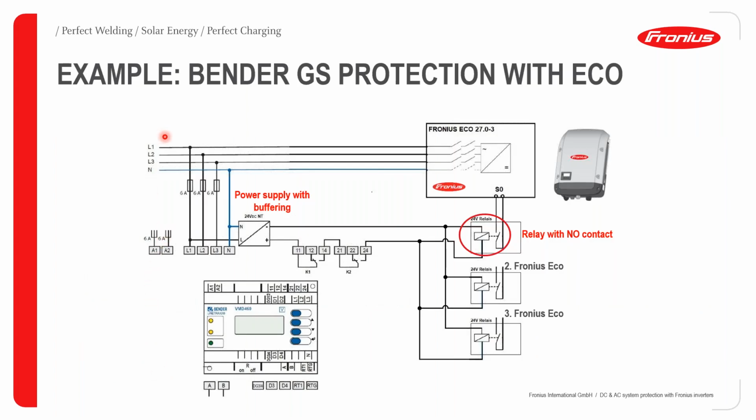Good. Now let's start with a typical example. So in this case, since we're using a German example, we're going to go with a German GS protection device, otherwise called the Bender GS protection. In this case, we're using the Eco. So for this case, as you can see in this line diagram, contact point, we have two contactors actually integrated inside this protection device. So it has here been represented, as you can see, by K1 and K2, all connected in series.